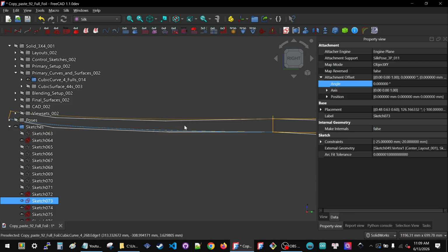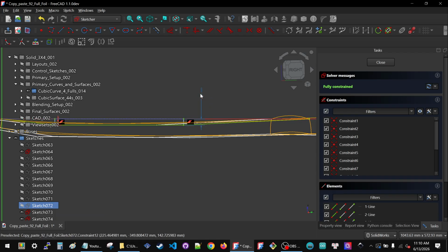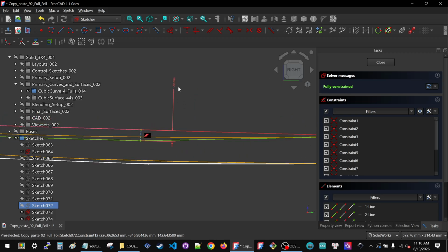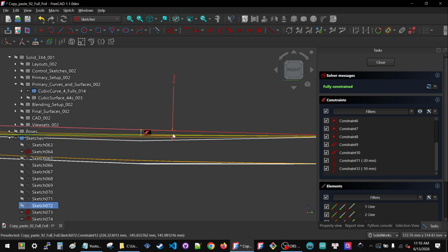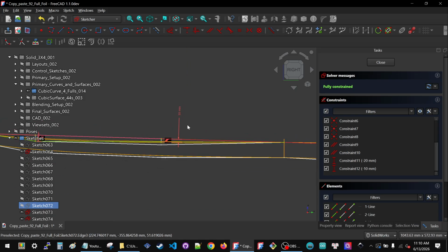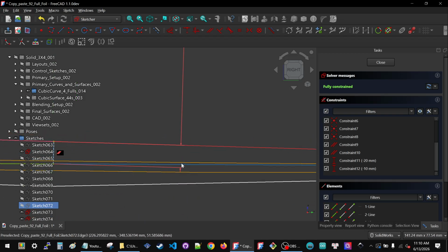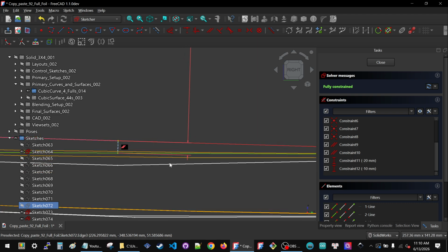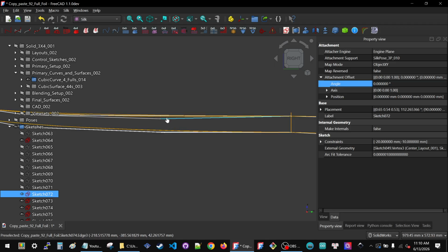Okay, that's fine, but now this guy also needs to be horizontal. Right now it's at minus 20. Get myself in the right side view. Let's try minus 10. You could have a really fancy scheme to control these dimensions. I'm just roughly using these linear dimensions here to create what I want. You could have a complex reference system that guarantees that these are always perfectly horizontal. I don't really care right now. This is still going slightly downward. Is that appropriate? That might be appropriate. Let's just do both of these.